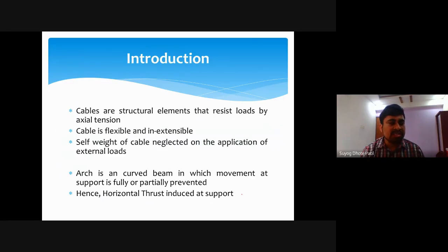Then during analysis, the self weight of the cable is neglected. Self weight of the member is neglected. Only externally applied forces, externally applied loads, are considered during that analysis. Basically, these are the assumptions during the analysis of any cable.